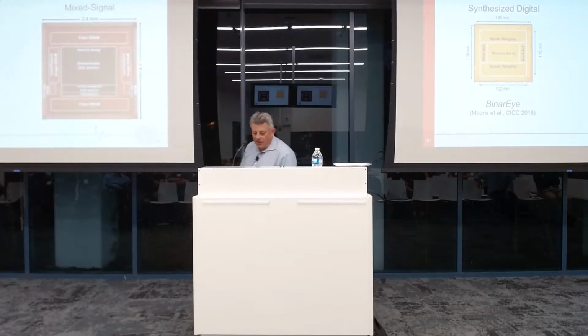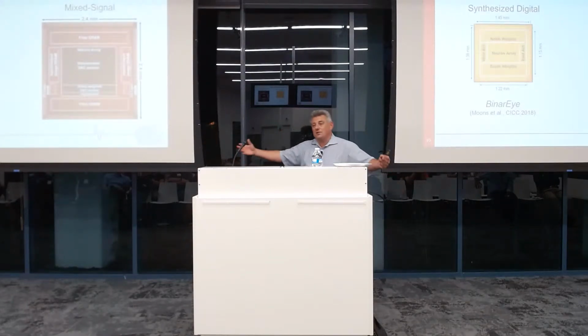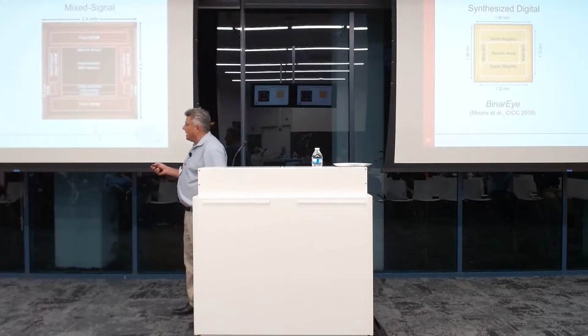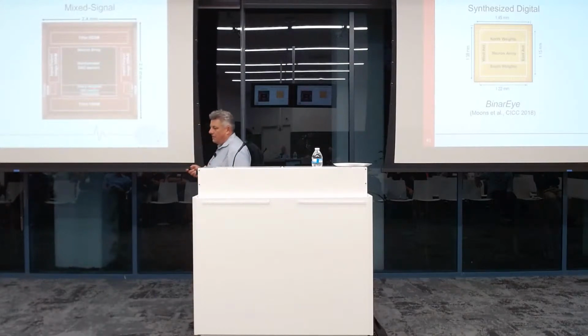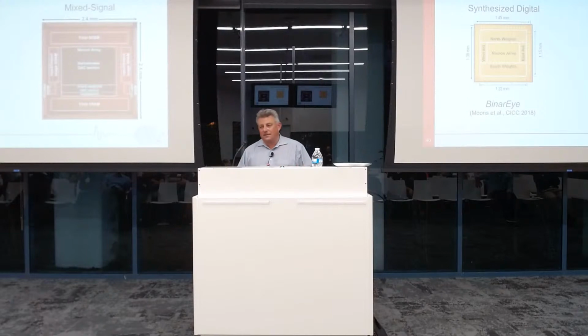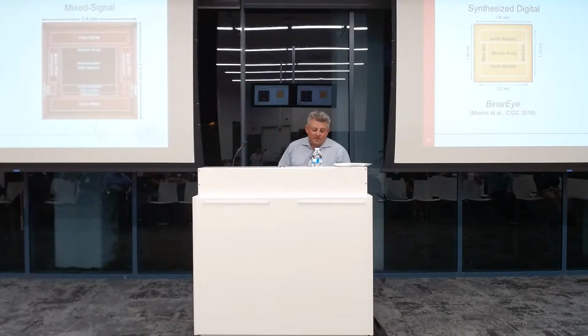So then, of course, we are getting pressed by questions. Oh, okay, but if you did the same architecture fully digital, how good would it be? So we did another chip, and that one we made fully digital, synthesized, place and route. And this thing not only was much smaller, it was also designed much faster. Obviously, it was much smaller because in the middle of this chip we did this fine-grained analog design, and analog designers are scared to death. They leave large spaces, and when grad students do analog layout for the first time, you can throw a football through these layouts. It's really not the most compact thing in the world. But anyway, it's not a horrible outcome.